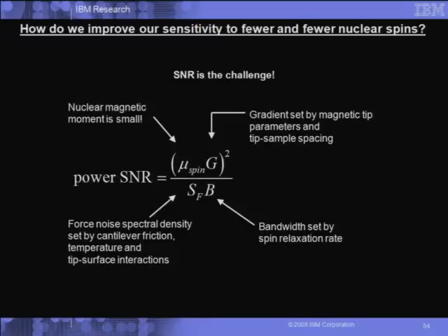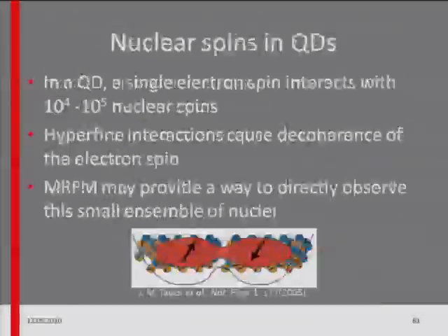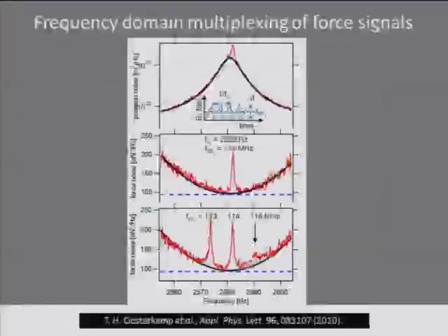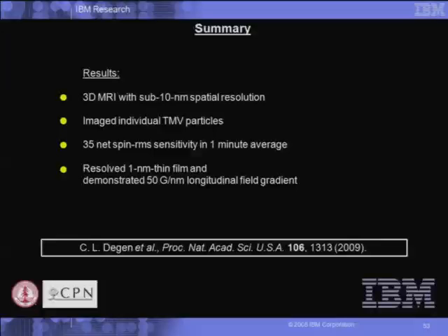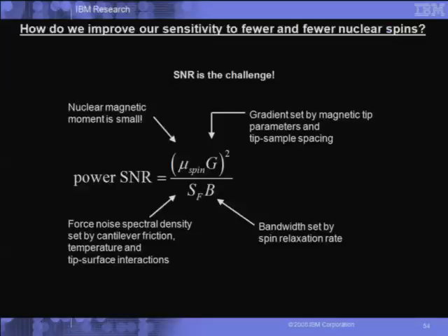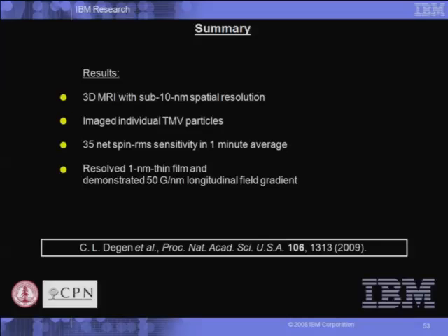You chose this integration time of 1 minute. So it's always hard to quantify this. Why 1 minute, and why could you not be better when you just integrate longer? I mean, if you always integrate longer, you can get the higher signal to noise, but it goes as the square root of time. So at some point, you don't. I was wondering why you're quoting a minute, usually you would quote a second. Yeah, right. Well, if we quote a second, it's not as good.